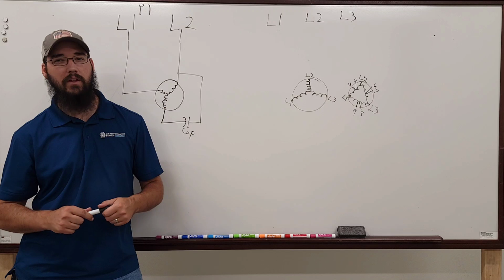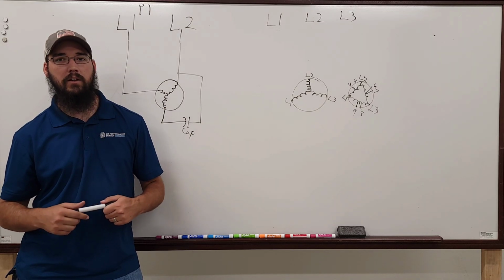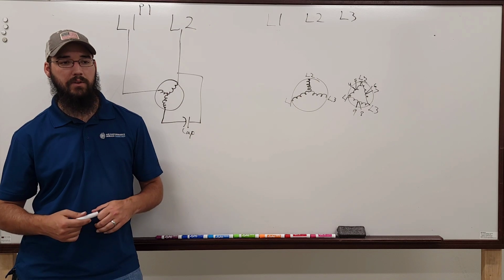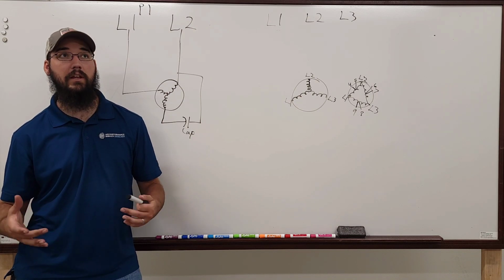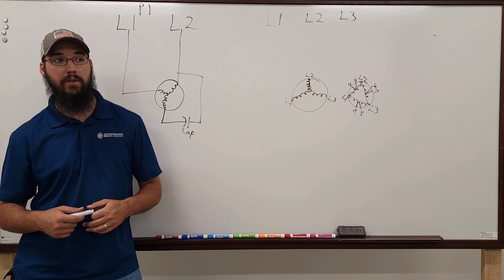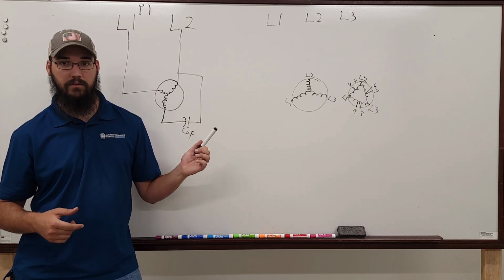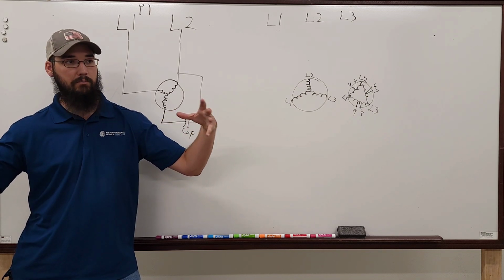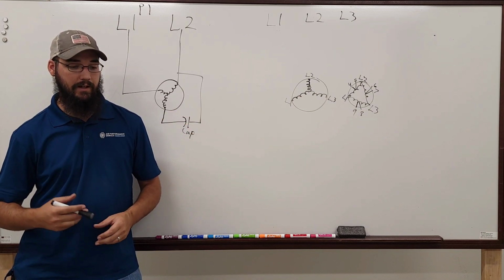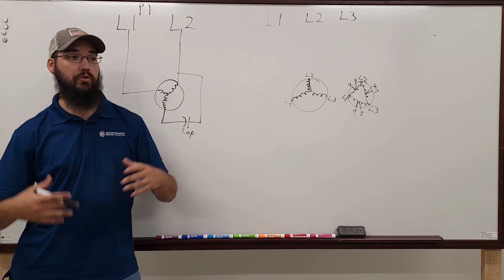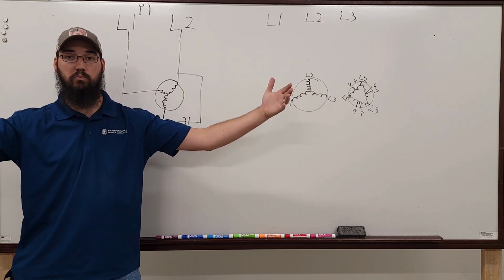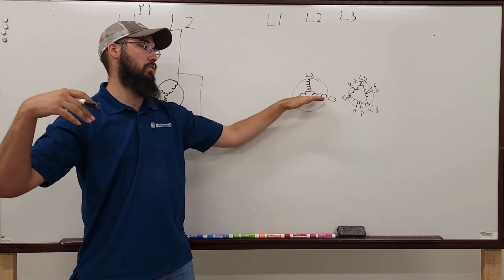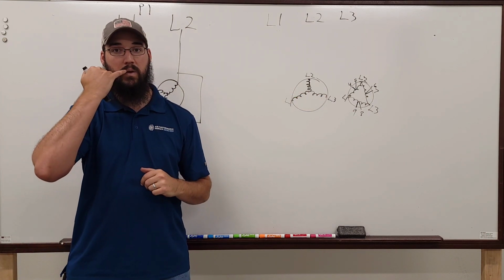So the 06Ds, I think, have a Y stator on them. But some of the bigger ones like the 06E, if I remember right, use a delta configuration. It's a bigger body compressor. Anyway, you get into screws and you start getting into those much larger motors. That's about the only time we start seeing this Y configuration pop up.